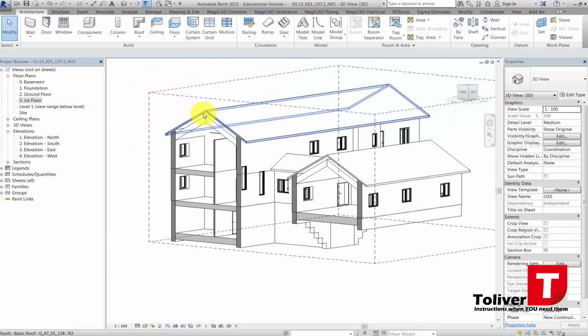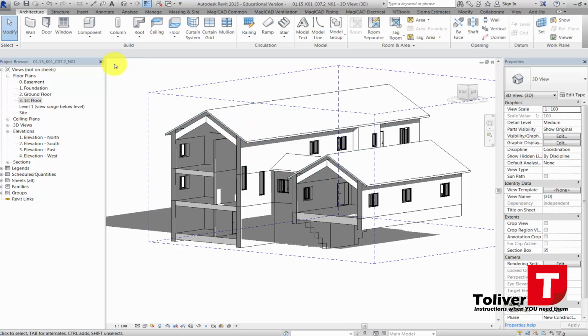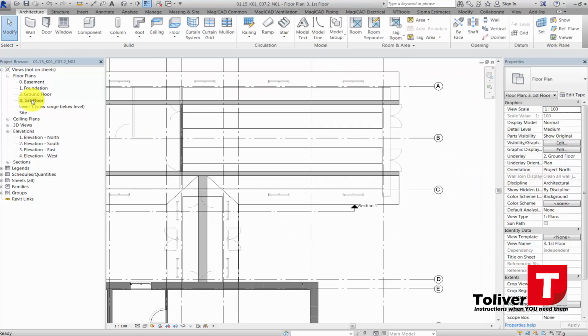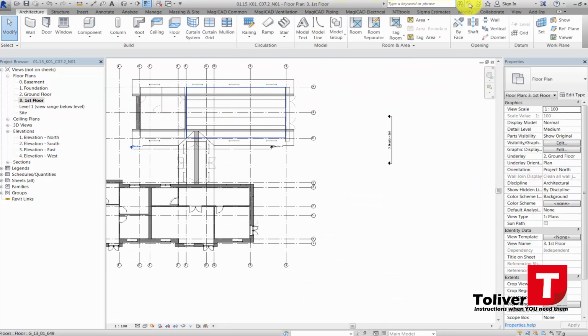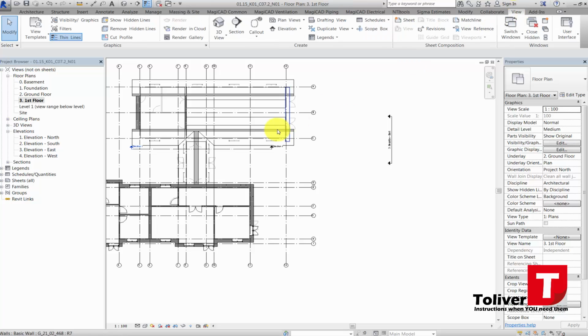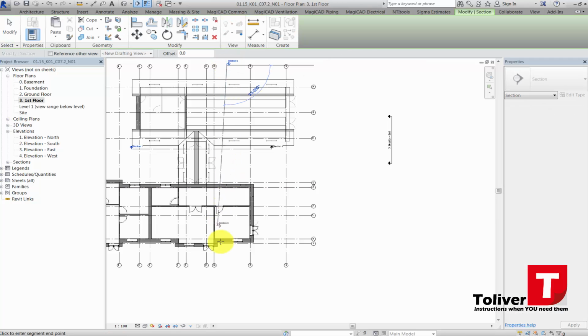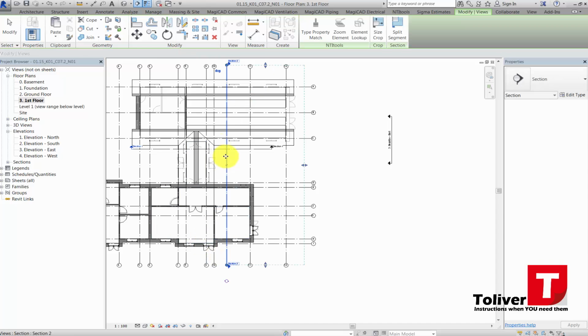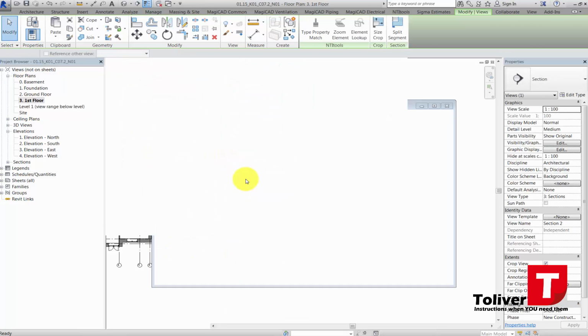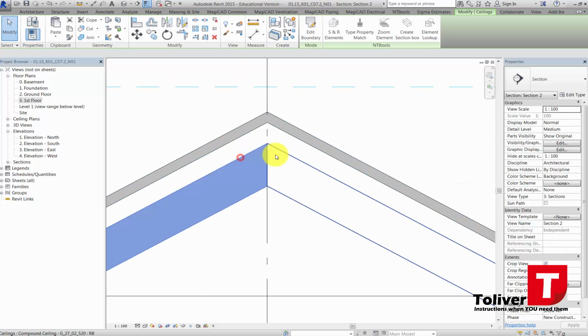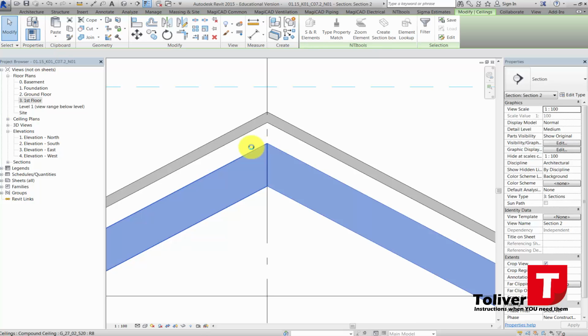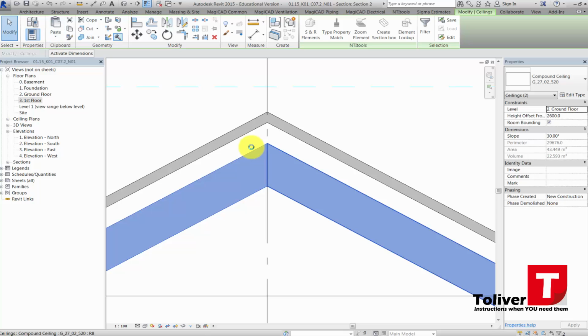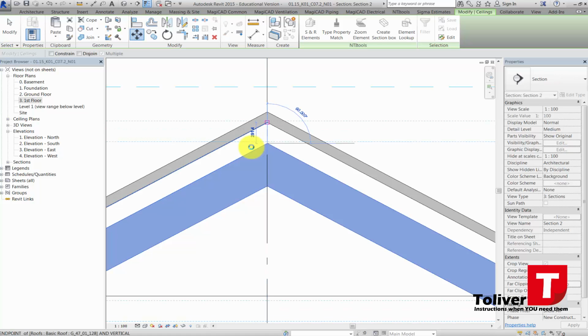The ceiling, of course, needs to be integrated with the roof up here. So I'm going to say first floor, and I'm going to go up to my view like this, and like we created a section here, I'm going to create a new section like this, and go to that view. What I then can do is pick these two ceilings here. I can say move by clicking here, or MV. I can grab a hold of the top points and drag it up there.